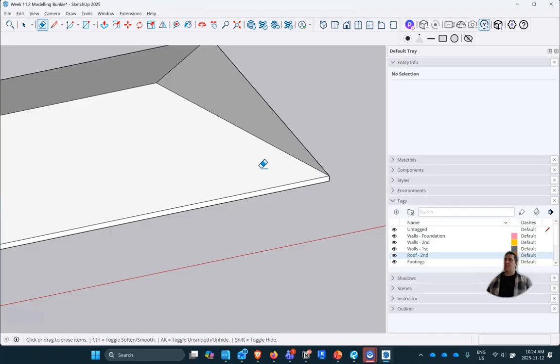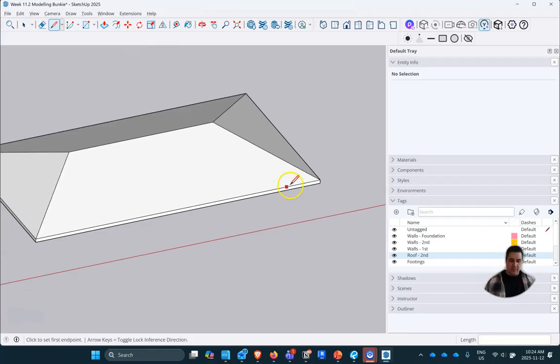class I did it with the same slope. This class I'm going to do it with a different slope. So say we wanted to add a dormer here, and let's make it 4 feet in. And so our 4 feet mark is somewhere right here. And then let's make our dormer 14 feet over. So not a nice number, not like our 12-foot number.